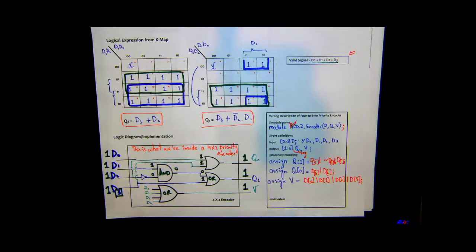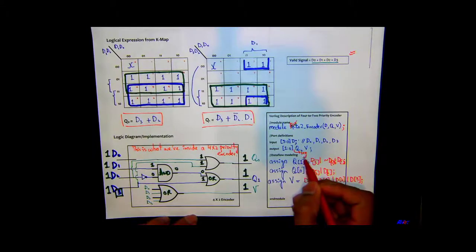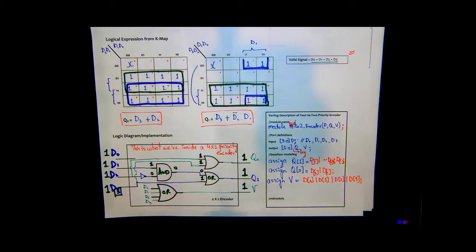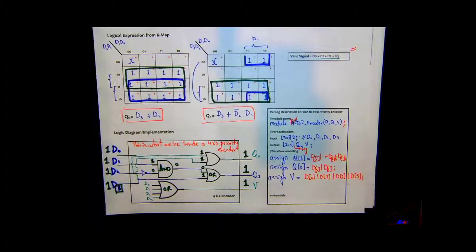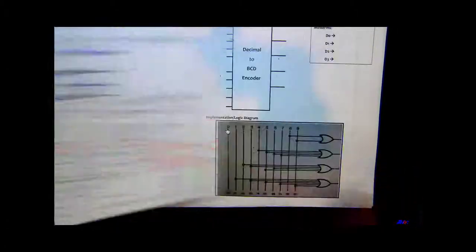So start just practicing now, because once we move on to the sequential circuits, this thing will be very necessary. It's not really necessary in the combinational circuits, and these are combinational circuits. So even if you don't add it, it won't have an effect upon the functionality. Once we start doing sequential circuits, you're going to have to declare these as registers. So it's good that you start making a habit of it from here. Everybody following me here?